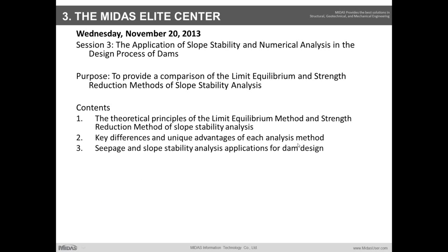And then as far as the last section, we'll discuss seepage and slope stability analysis for dam design. I mentioned this earlier, how seepage analysis is typically used in coupled analysis with slope stability projects. In other words, I'll go over step-by-step how you would do a seepage analysis, and then you take those results, or you take your pore water pressure loads and apply them to your slope stability analysis, and how that would affect your dam design.